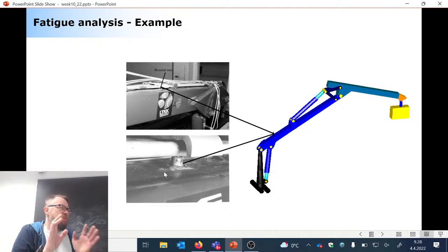Welded stud. Remember what I just said about welding. Welding is a dangerous business to do because of 2 things: initial cracks and high residual stresses. Because of these 2 lethal aspects, you want to take your welding away from highly stressed areas as much as you can.